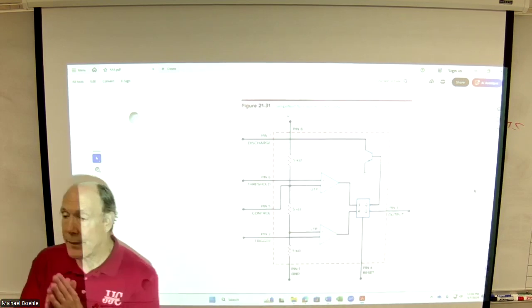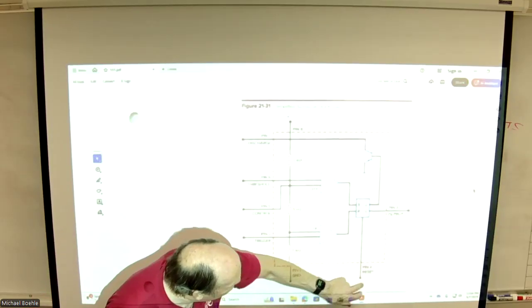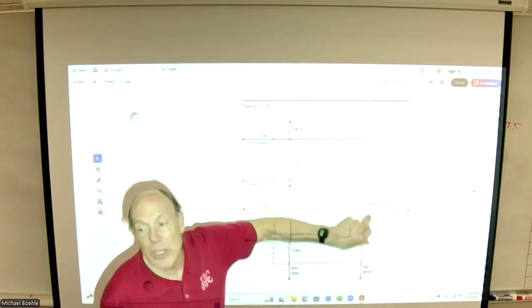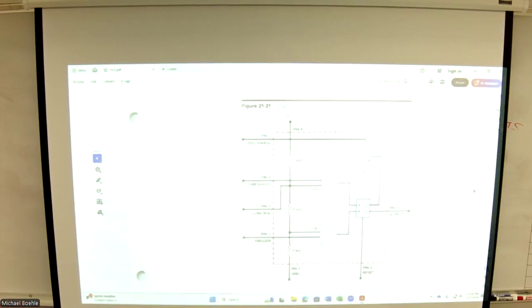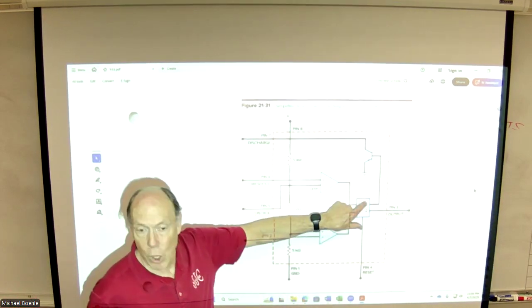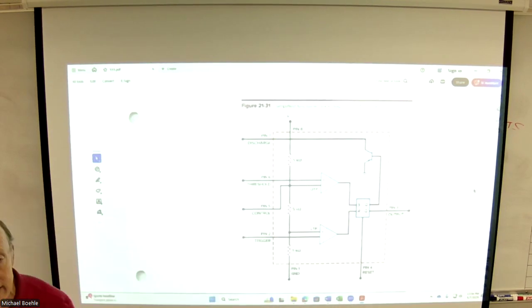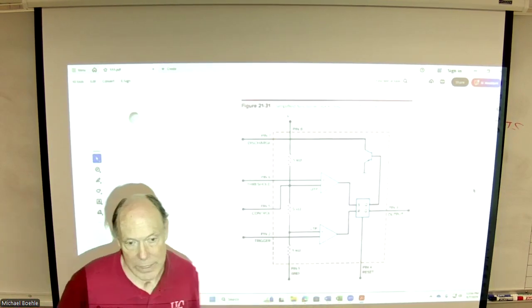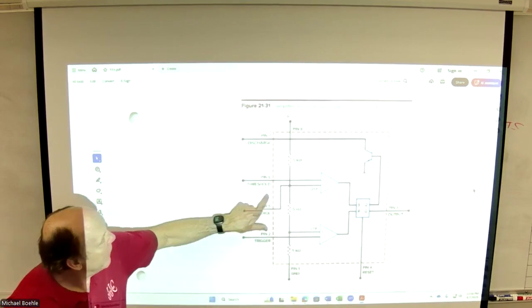All right. Now, we do have the ability, an external pin 4 allows me to reset that flip-flop. So if I reset the flip-flop, that basically makes Q go low, not Q goes high. So I can basically force the output high at any time using that input. Now, you'll notice that there's another pin here.